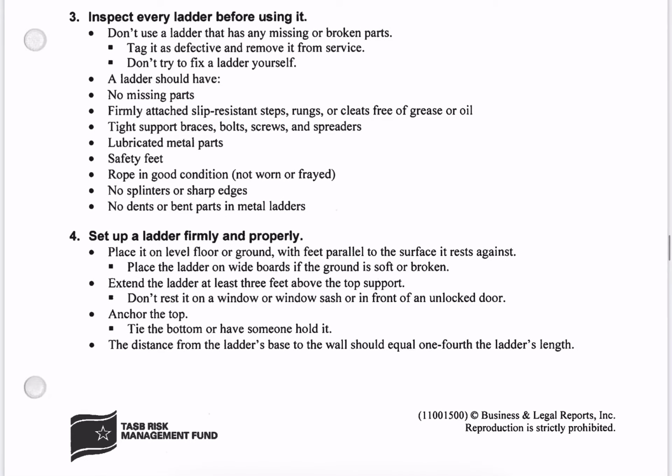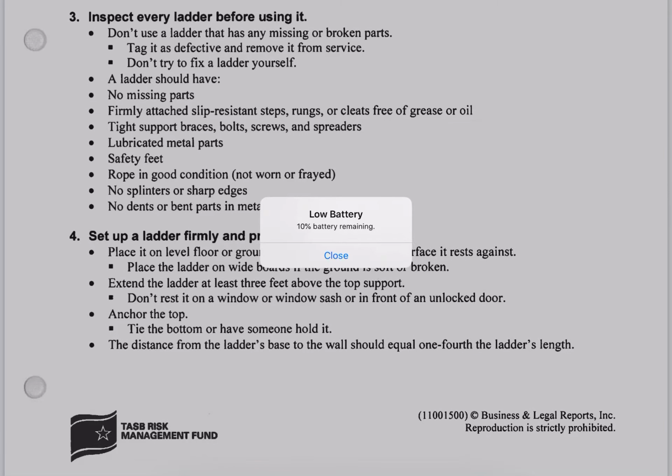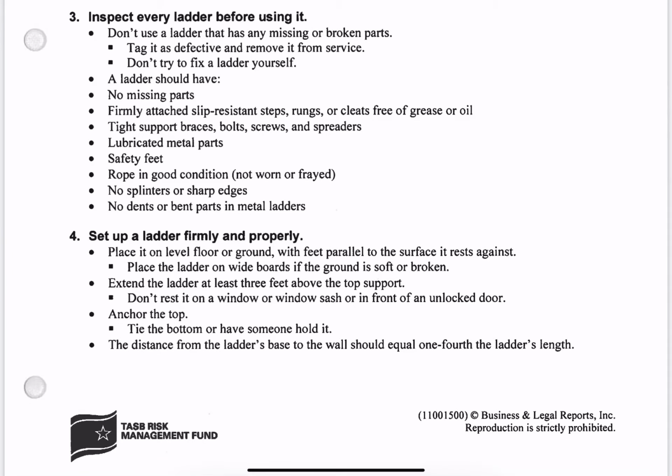Number 3, inspect every ladder before using it. Don't use a ladder that has any missing or broken parts. Tag it as defective and remove it from service. Don't try to fix a ladder yourself.